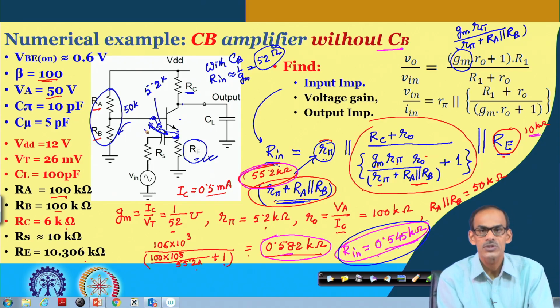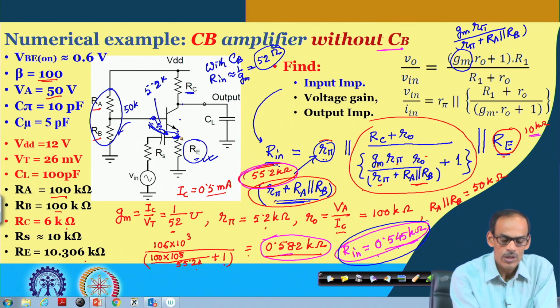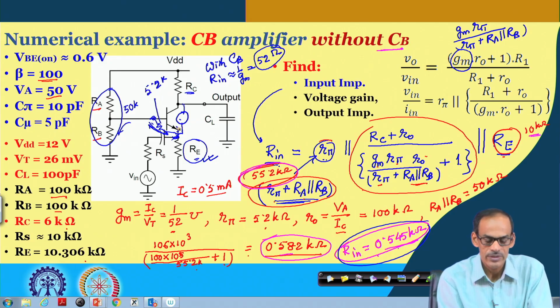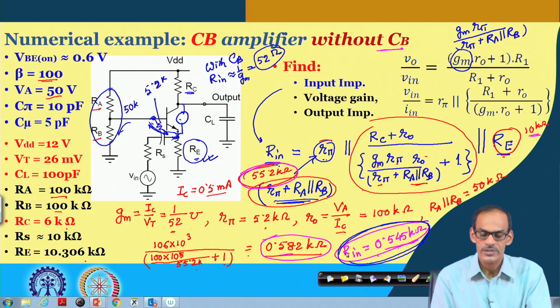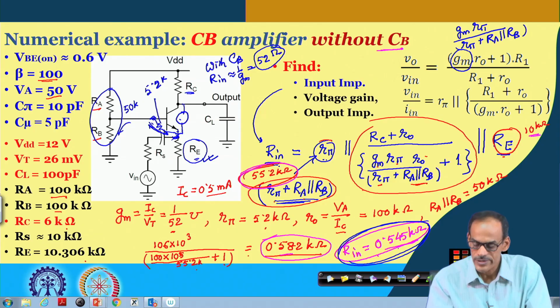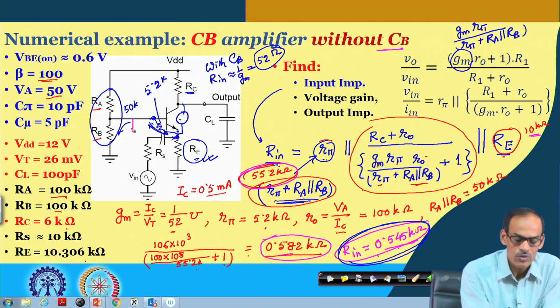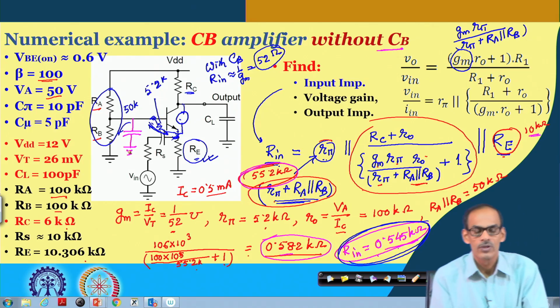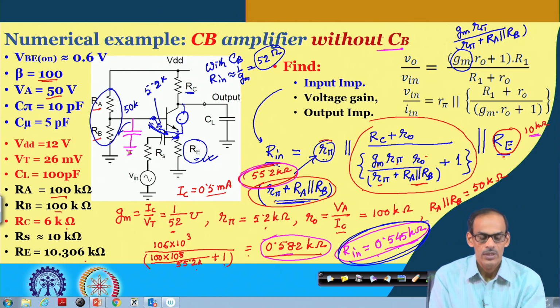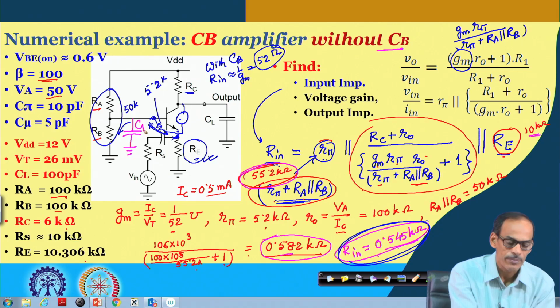So, now it is very obvious that whatever the stimulus you are putting voltage wise, only 1/10 is coming here. So, that gives you an intuition that the equivalent GM or equivalent input impedance coming from 1 by GM is getting changed by a factor of 10. So, that is how the input resistance is getting increased. So, the bottom line here, even if it is not mentioned explicitly, we have to keep in mind that at the base node we should ensure that this is signal wise AC ground.